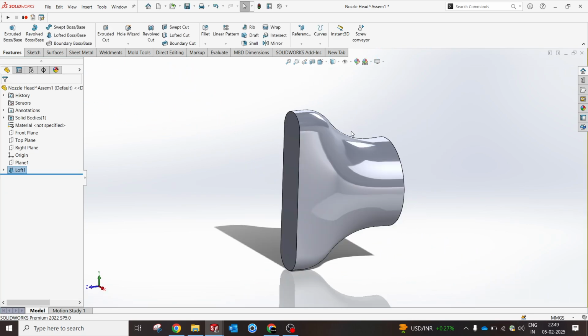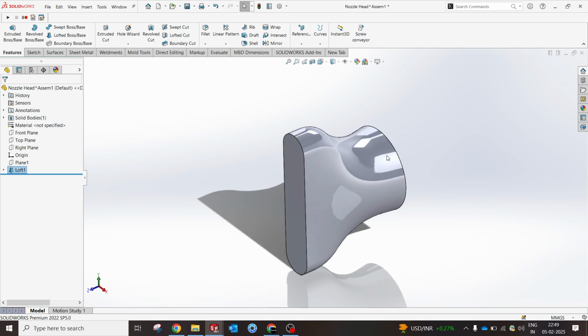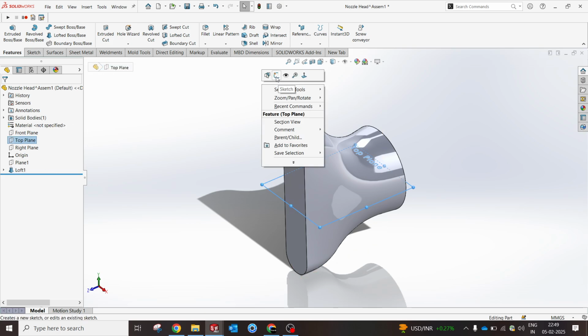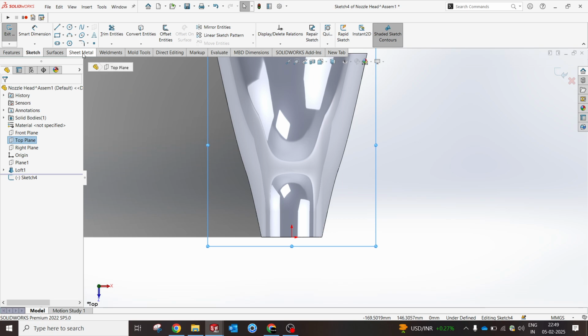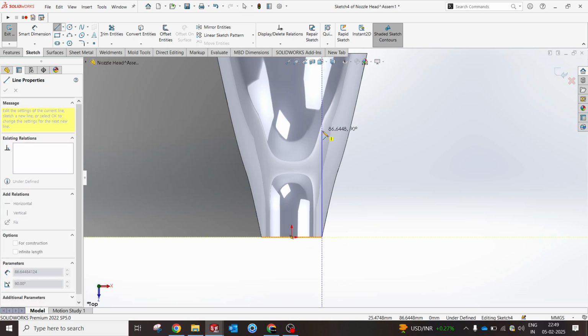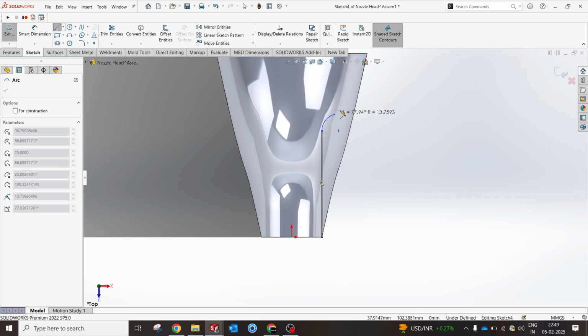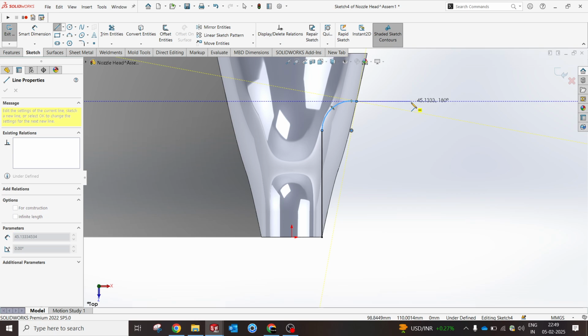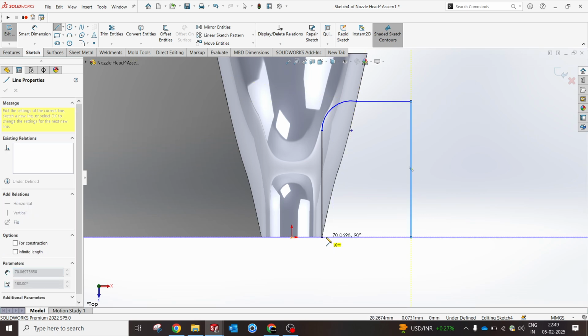You can play with the profile however you want, you have a lot of options, like you can create multiple guide curves however you want. You guys can play, so there won't be any issue at all. Yep. So now I'm gonna use a stop line to make sure my other profile, which I want to have a flat surface over here. And again, as I said, I'm gonna create a arc. I'm gonna use this option.